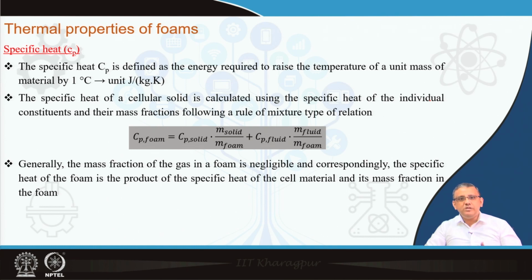and again the specific heat of foams, unlike the melting point or expansion coefficient, depends upon the amount of porosity, but mostly it depends upon the amount and not the shape of the pores. So, this rule of mixtures is typically used to find out the specific heat of the foams with respect to the specific heat of the solid and the fluid materials.